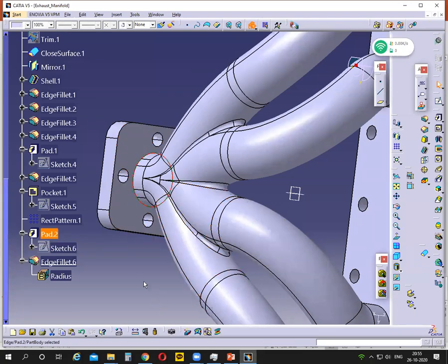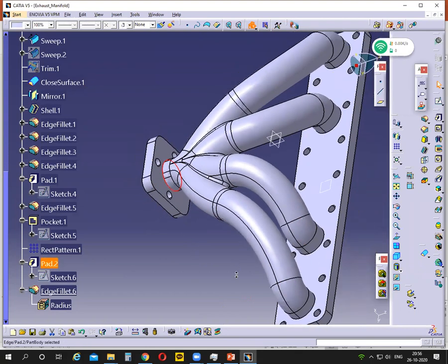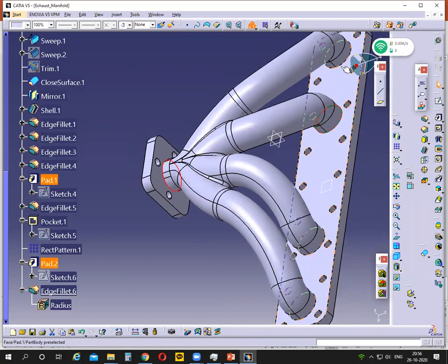If you don't have fillets, there are sharp edges, so stress concentration is more because the area is very small at that sharp edge. So more stress concentration on the sharp edges. To expand that area along that particular point, we provide fillets, to reduce the stress concentration on edges.